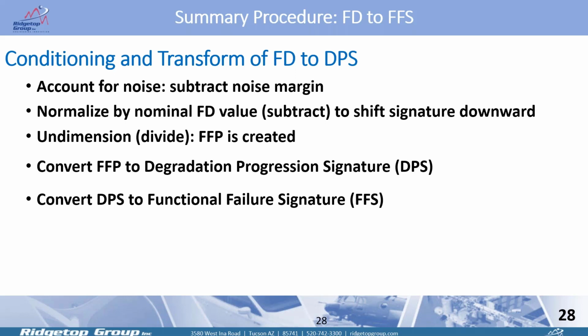Then we divide it by an appropriate divisor so that we keep the scale range within reason. And we've also gotten rid of the units of measure. So instead of kilohertz or milliwatts or ohms, all we have is a number, a ratio, and that's nice. And you choose your divisor so that under normal circumstances, a signal below zero means it is perfectly good, and above 1 means it's failed.